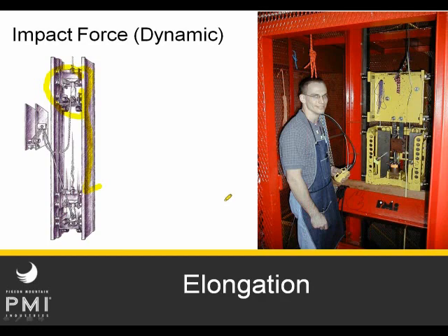So it's about a factor 2 fall. It's a factor 1.8 fall, so it's a lot higher, and it has to reduce the force of that falling mass to 12 kilonewtons or less. So that's why dynamic ropes are better for use in lead climbing falls, but static ropes can be used in lesser falls without any problem.